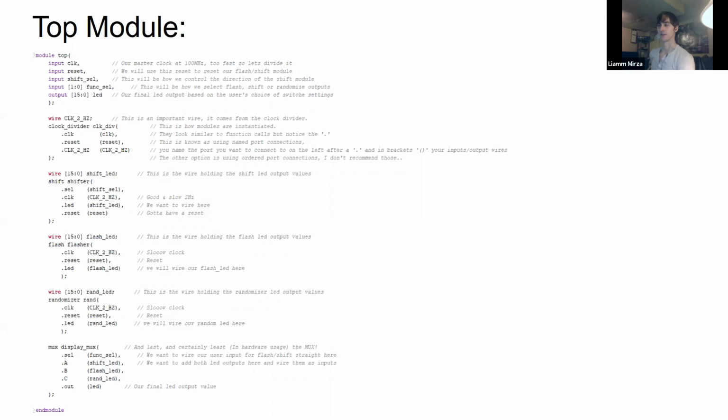I think that's the next part, generating the bit stream, actually. So if you guys are finished with this and everything looks good, I would recommend running a synthesis and making sure you have no warnings at all, like none. The next step after this is to make sure this is your top module. You right click on it, because otherwise you'll generate a bit stream for your behavioral.